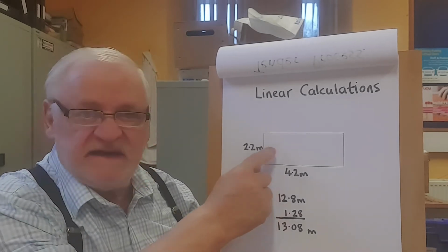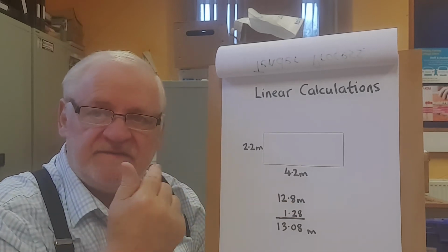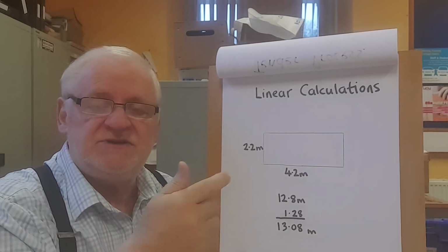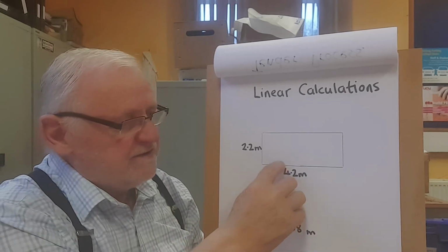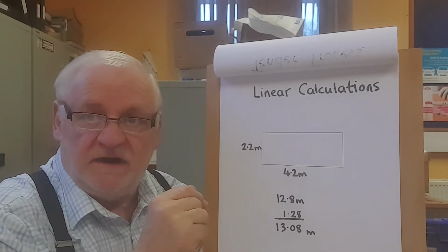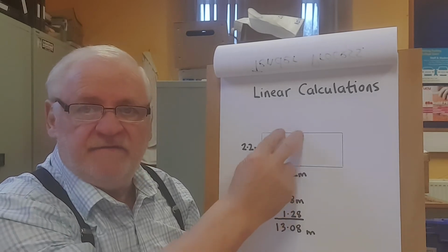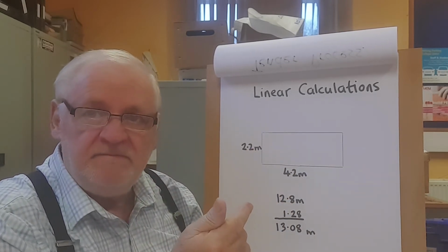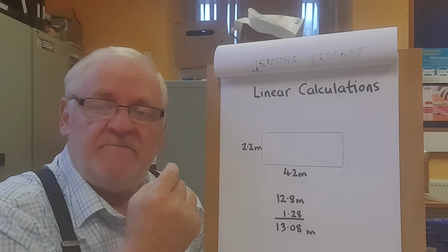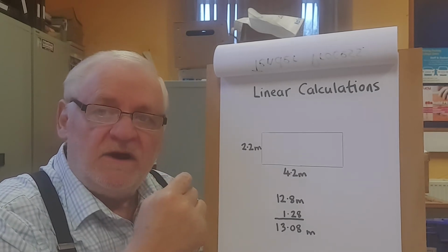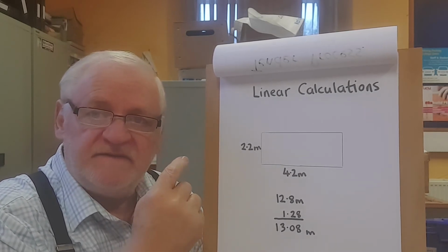And you might have 6 rooms like this, and you might have to work out the overall meterage of the whole thing. If there were doors in the room and you're going to order the architrave, then obviously you'd remove the size of the architrave from the length of timber that you need, but also you will have to then order the architrave to go on both sides of the door.